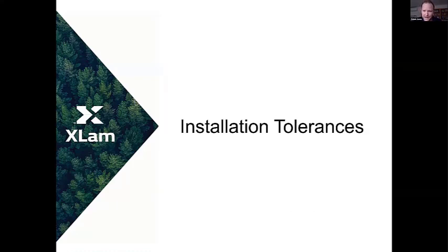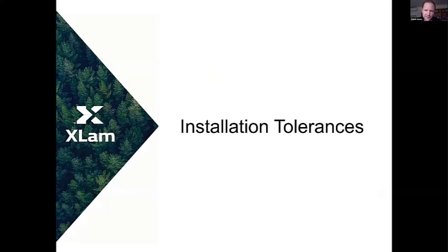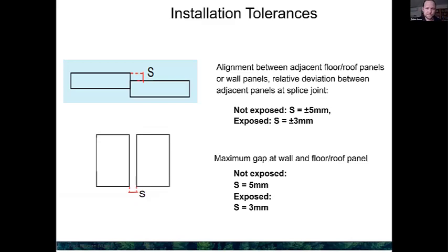All right, so now the final part of tolerance is installation tolerances. As I was saying earlier, when you're trying to fit things together, you can't expect perfect accuracy from the installers on site. The installation tolerance is going to be very different based on what you might be installing. It might be a very snug tight naturally, or sometimes it might be harder to get that snug tight on site, and there might be a bit more movement, particularly if you've got multiple panels next to each other. You might accumulate as you go across. So there's a bit of nuance in installation tolerances, but we can help with some crude assumptions.